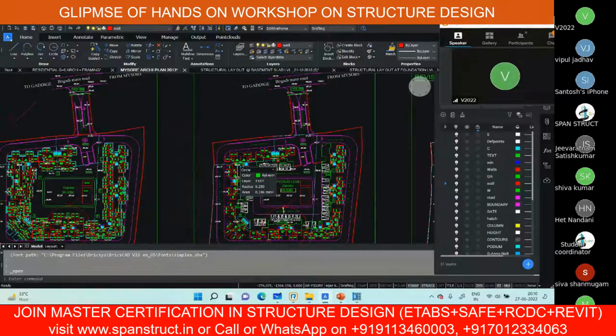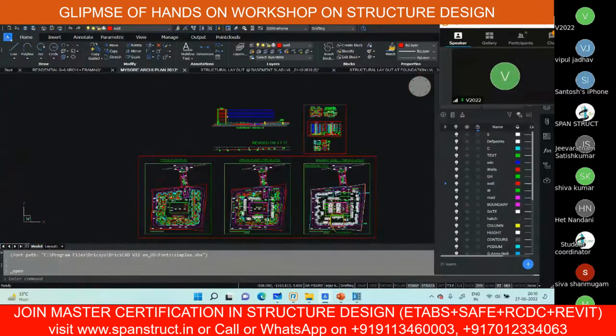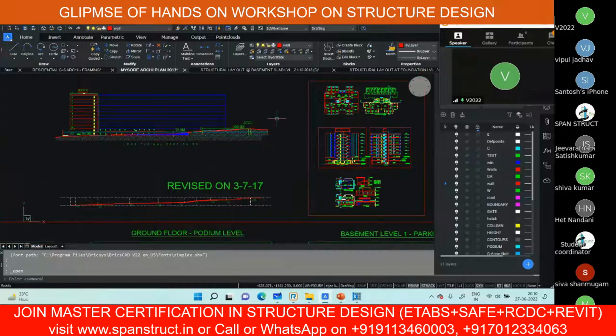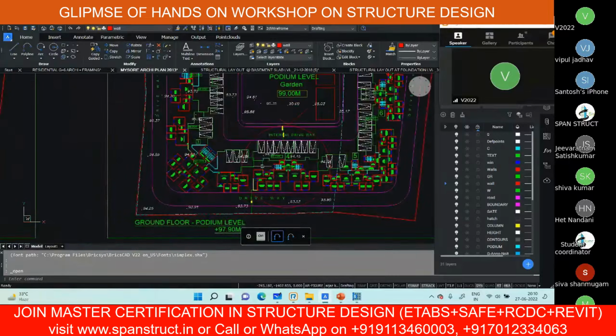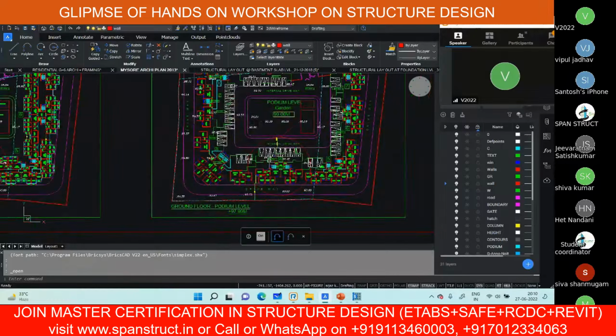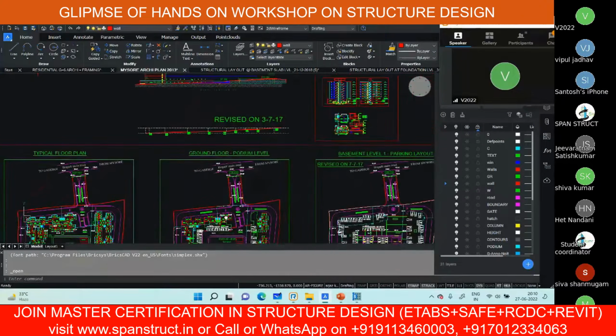The first thing which you will get from the architect is this. And here what you have to do is read the plan very well. You cannot directly start building your structural framing plan. You have to look at the elevations, look at the sections, and look at how you're going to give the columns and all like that. That means you have to completely read the architectural plan, sections and elevation here.